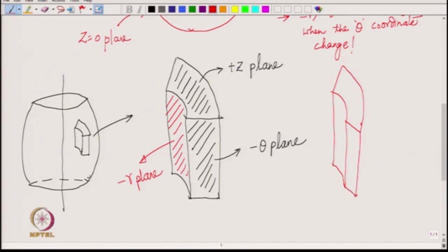All right. The top face, which is the z plane. So, on that we will have T z, traction on the z plane, and it will have the normal component which will be sigma z z. See, it is the positive z plane. So, sigma z z is going to point in the positive z direction. So, we have sigma z z here.